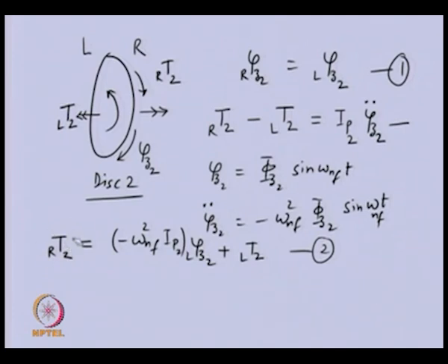Here also you can see this is the right side torque of disk 2, and here the field variables, displacement and torque, are at the left side, because in this we have attached the left one, since right and left angular displacements are the same. For our convenience, we have added this left here. Now, we can combine these two equations 1 and 2 in matrix form.